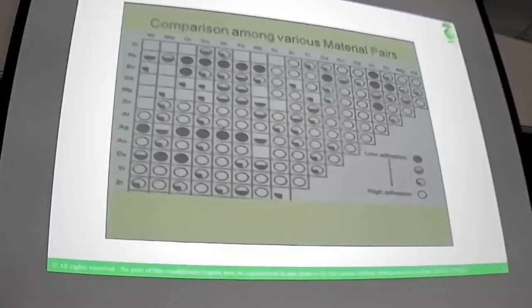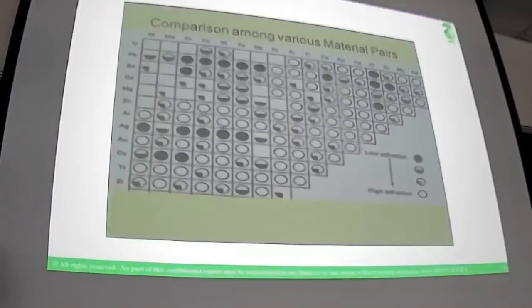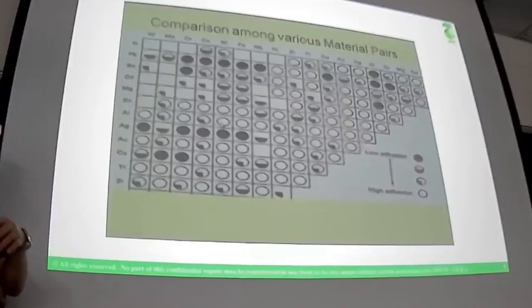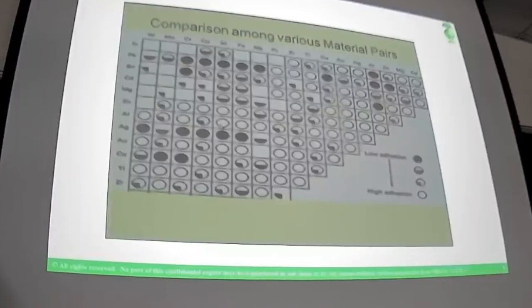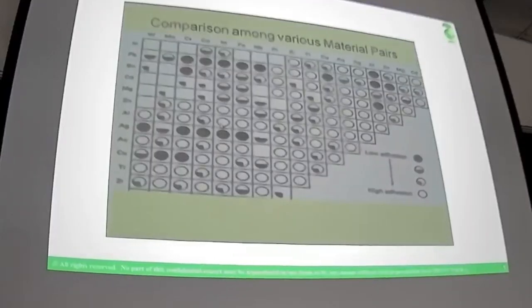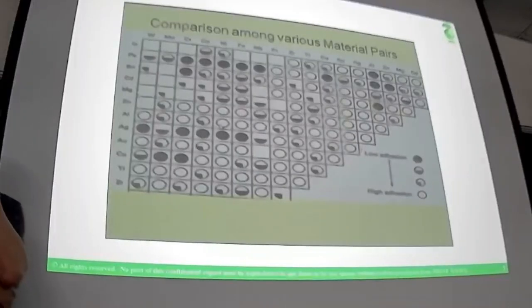your component material properly. If one is a fixed frame and another one is a moving member, then you need to choose the correct material. In mechanical design, the moving and fixed parts are very important. If you choose the same or similar materials, they will actually stick together and have a larger coefficient of friction. So this is the figure.